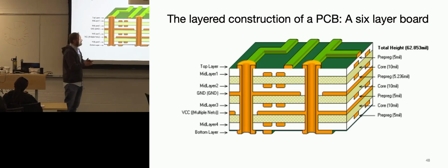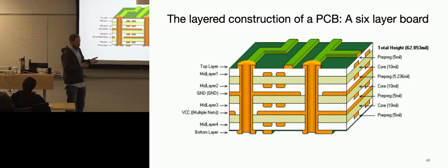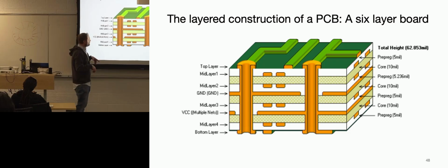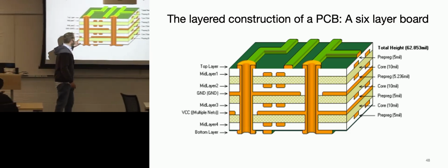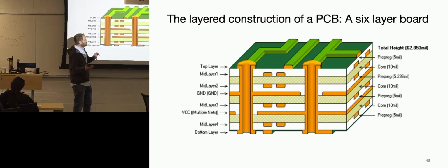I teach all my students, typically we start with a 4-layer board. So components on top and bottom. 1 layer, it doesn't matter which one it is, it should be a ground plane. You should pour copper. You tell your tool, pour copper. Altium still calls it pouring copper. And that will just be a ground plane that goes through everything. You don't necessarily need a power plane for most designs.